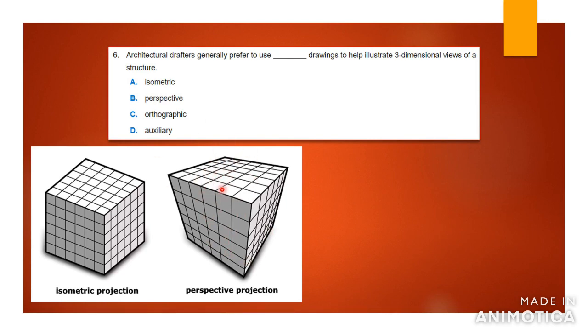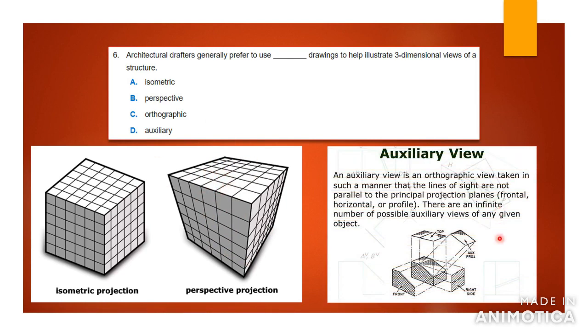Okay, and also auxiliary views are mostly for drawings that are flat or two-dimensional on the paper. If you want to know the measurement of an awkward surface, you would project it out. So this is auxiliary. Auxiliary is something that is not on the 3 planes, the top, the right, or the left. It's on a different plane, and as you can see here, it is slanted slightly, so it's sticking out on a different plane. Okay, and it gets awkward if you're looking at an auxiliary view.